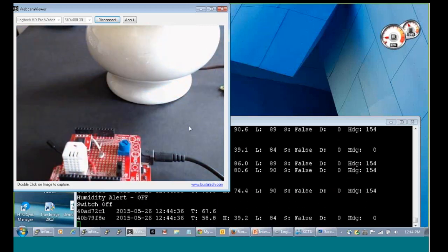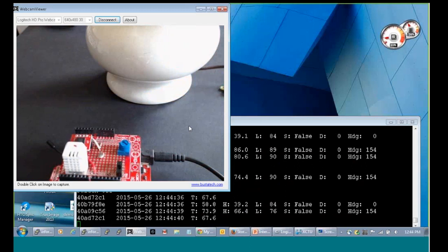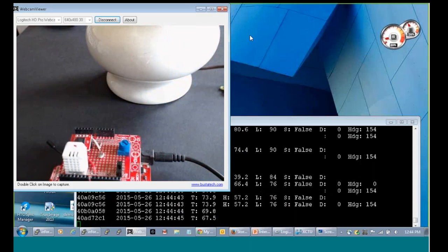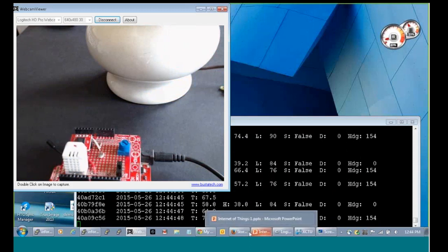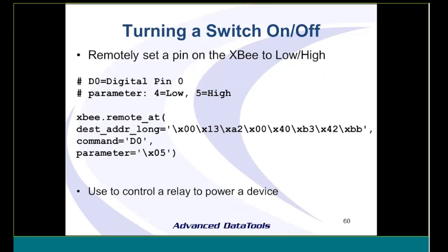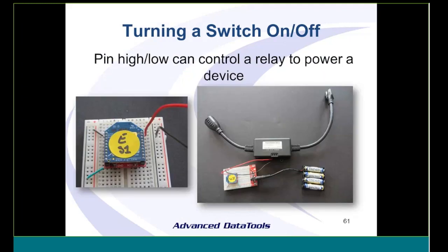That lamp is controlled through another wireless device. It is not connected directly to our gateway. And I can show the example of that. So the way we did this, we're using another XBee radio connected to a little board, and we're simply saying, hey, we want to turn something on, turn pin 1 on the XBee to on, so power that pin, and then we can use that to trigger a relay in which the light is plugged in. And this is all it is.